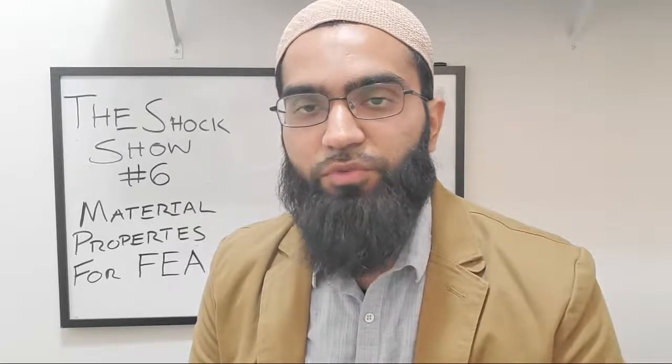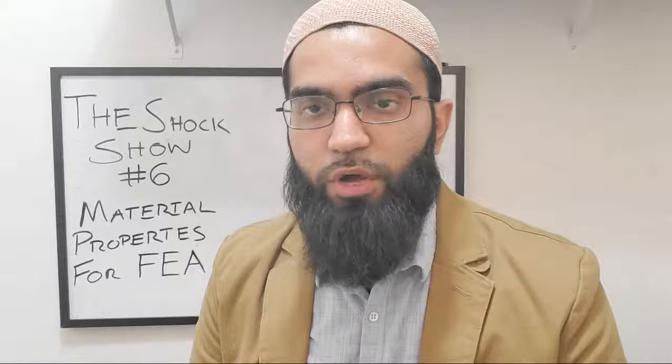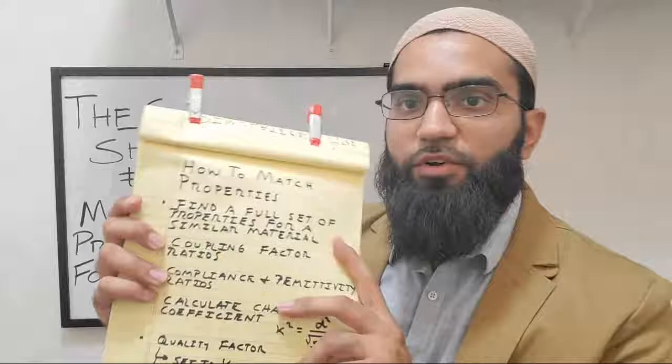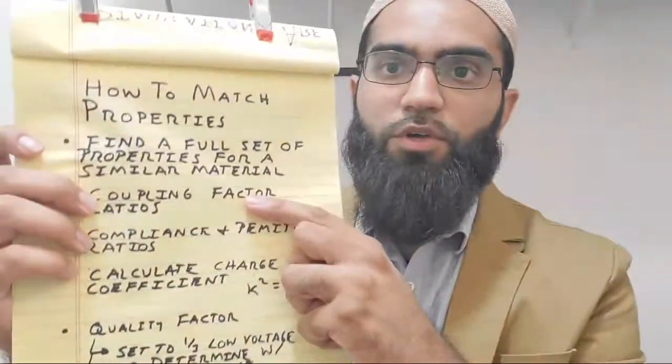Let's say we measured K31, the coupling factor of the 3-1 mode, for your new material. In order to start that transfer of comparisons, you have to create a coupling factor ratio. So you have the K31 of your material and the K31 of the full data set material you found, perhaps from a literature resource that provided all those properties.